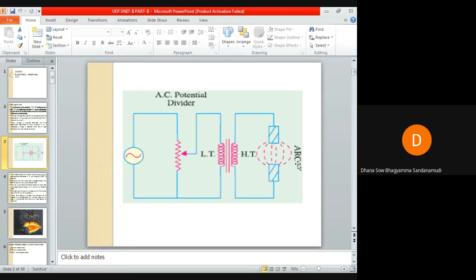The substance that is to be heated by this arc can be a solid, liquid or gaseous substance. When the heating is direct, the material is directly placed in contact with the electrodes. If the substance being heated is placed directly in contact with the electrode, that is known as direct heating. You can call it direct arc heating.